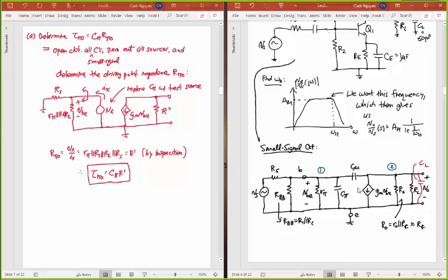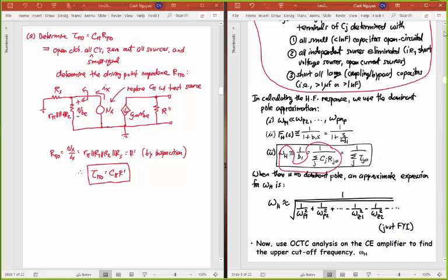We took this circuit, and we're focusing now on C pi. We want to get the driving point resistance associated with C pi, because when we multiply C pi by that driving point resistance R pi naught, we get that time constant that we want. That adds to other time constants in the denominator of 1 over that summation that gives us the cutoff frequency, the high frequency cutoff. And so to get that driving point resistance, we did exactly what this thing said.